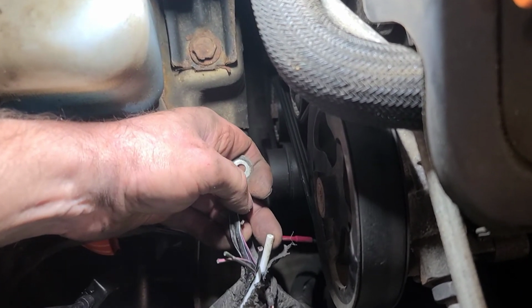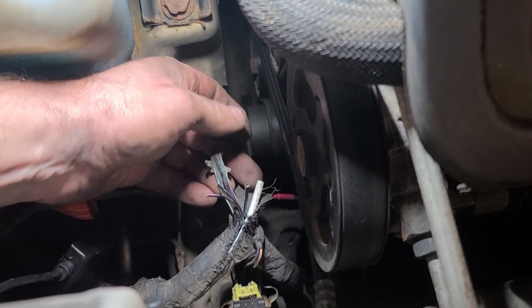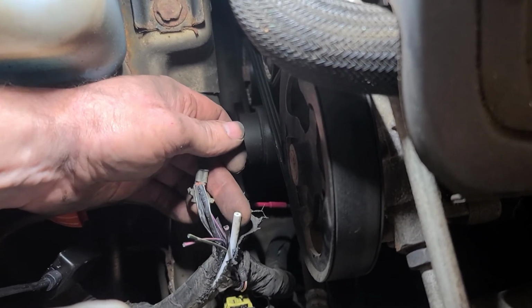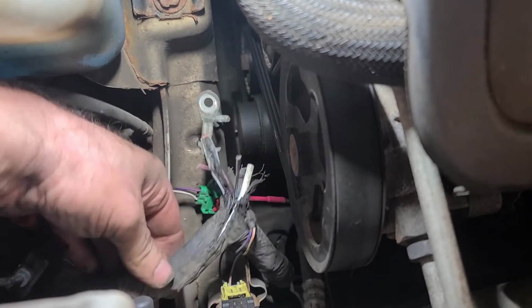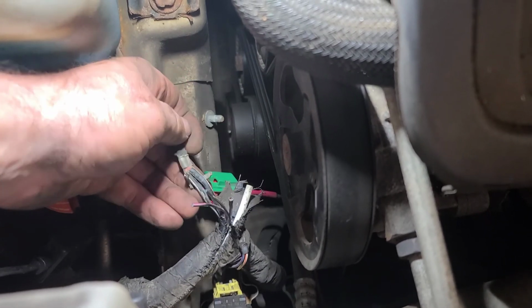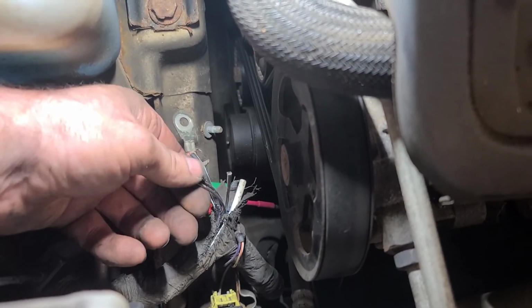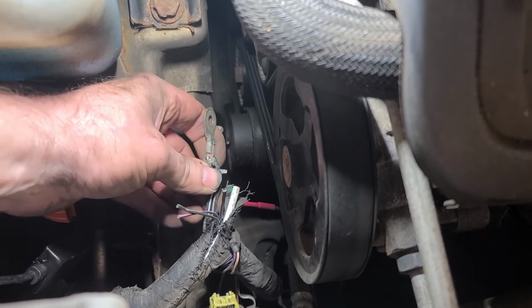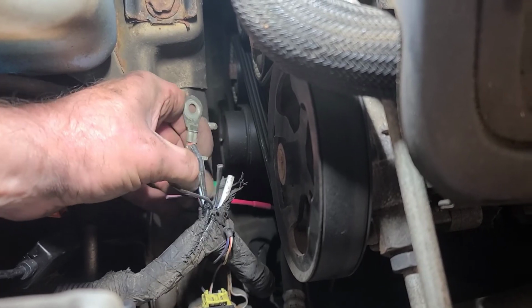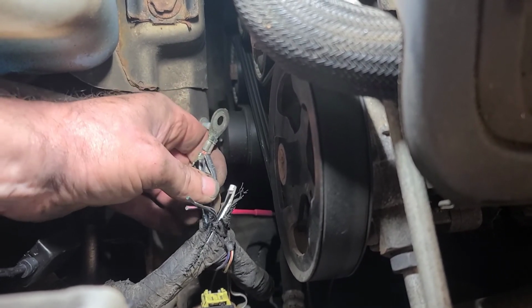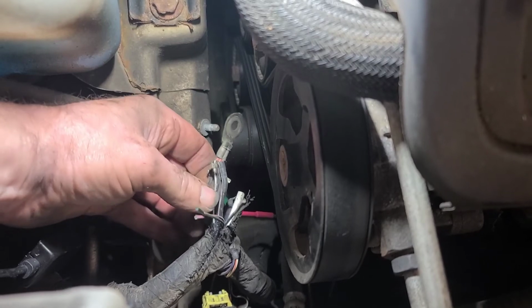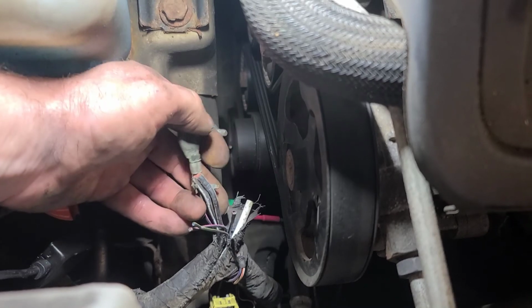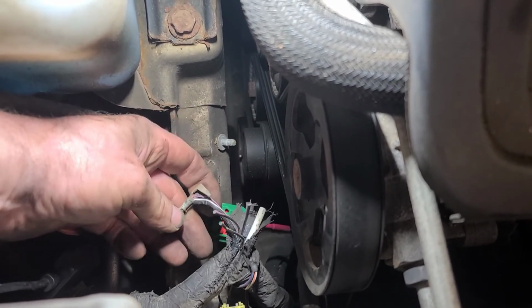The factory put a piece of plastic in here so that the wiring harness didn't vibrate and break off. That's what this white plastic piece is in here, just a reinforcement. But we're going to extend all these wires and probably put individual eyelets, because there's like 1, 2, 3, 6 wires in here. 6 or 7. 7 ground wires in that, sharing that.